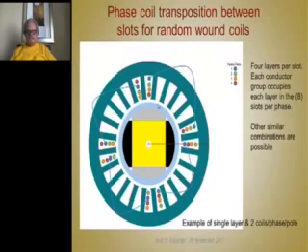You break the parallel conductors up into 4 groups, and you divide the slot depth into 4 sections: 1, 2, 3, 4. They're color coded here. So on the first coil, you put group 1 in position 1. In the second coil, you put group 1 in position 4, and then in position 3, and then position 2. Or I should have gone the other way: group 1, 2, 3, and 4.